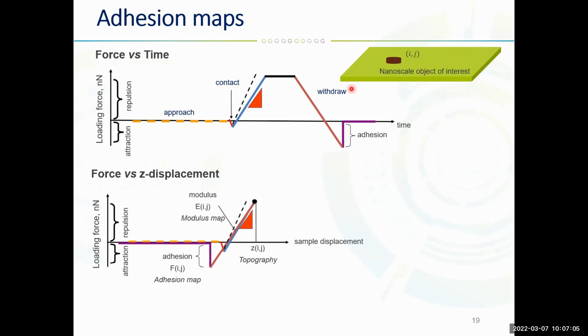If we come back to these schematics again, for instance, the loading force can be indicated as a dot somewhere on the sample. This point gives you the displacement of the substrate that's required to achieve this loading force. And then we have this position that you can use for further calculations, from this force versus displacement curve that you can get after running the AFM experiment.